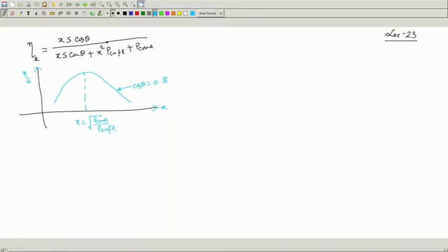And if you repeat the same thing for other power factors, these curves will be like this. This may be power factor cos theta 1, and for lower power factor it may be 0.6. No point in attaching leading or lagging, efficiency will remain the same.